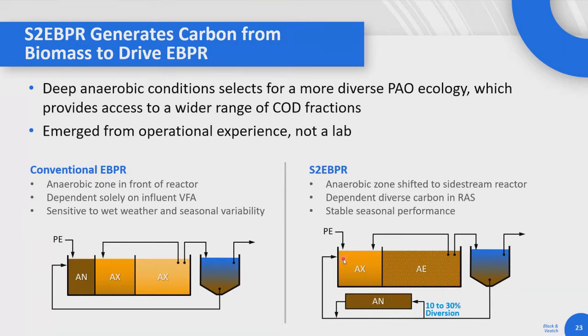So when they come around to the influent, we've stored up that PHA, and now they're going to use that PHA to store poly P, and that takes up phosphorus. So instead of having this be all in the same flow diagram, it's more like carbon storage here, phosphorus uptake here.